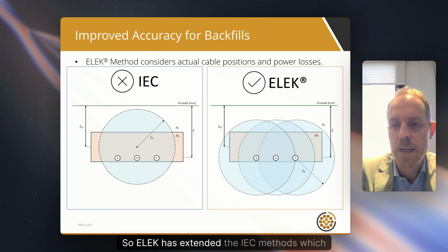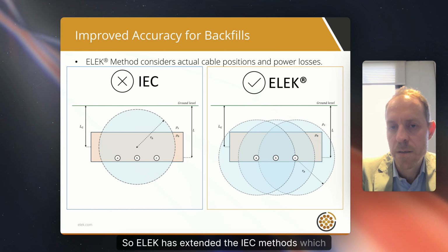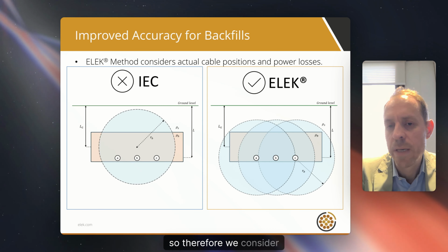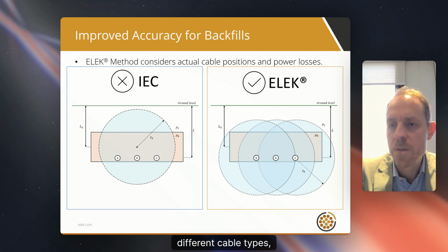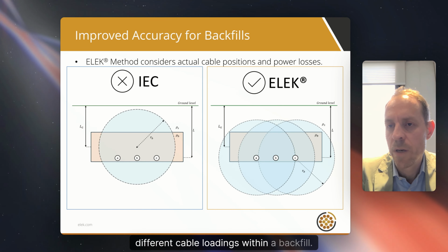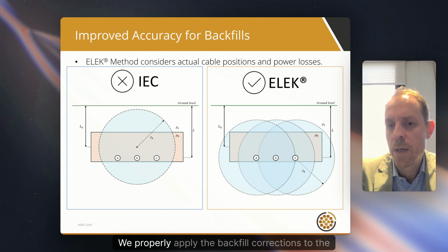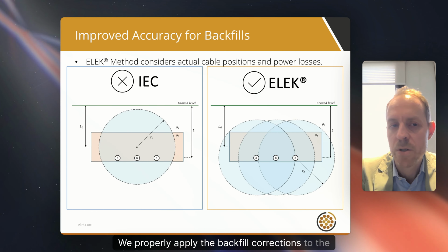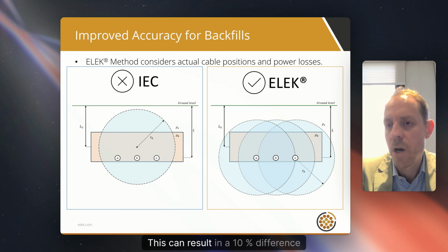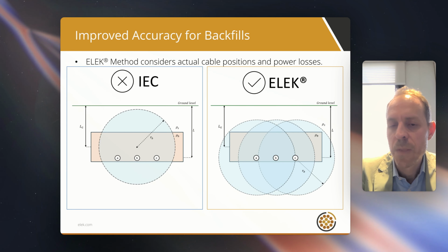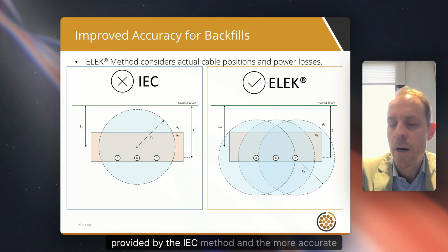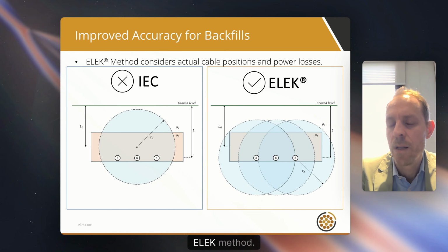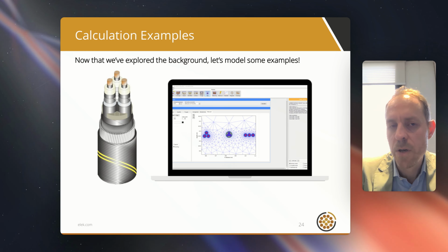So ELEK has extended the IEC methods, so we consider the exact cable positions, different cable types, and different cable loadings within a backfill, and we properly apply the backfill corrections to the calculations. This can result in a 10% difference in the cable rating calculations between the IEC method and the more accurate ELEK method.